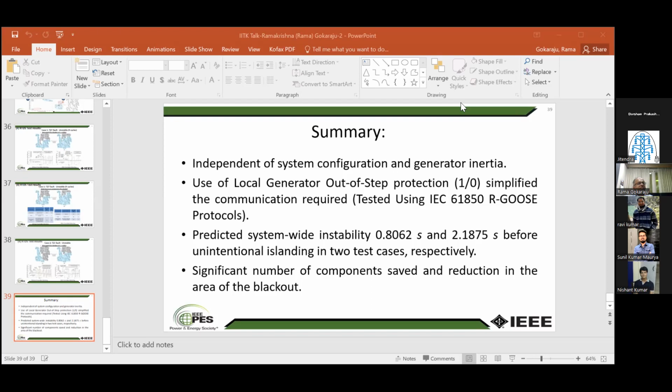It was between 2000 and 2010. The reason they put the whole system on RTDS was that they key in the operating scenarios and the credible contingencies they create, and they want to see how the system is going to evolve in terms of transient stability, the line overloads, and so on. They did this to do this kind of analysis quickly for the planning department.